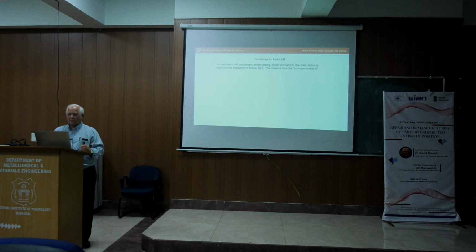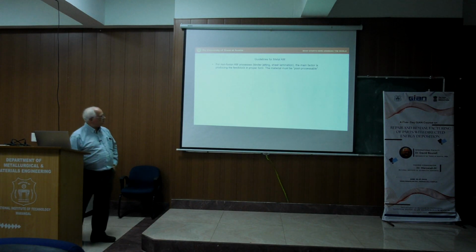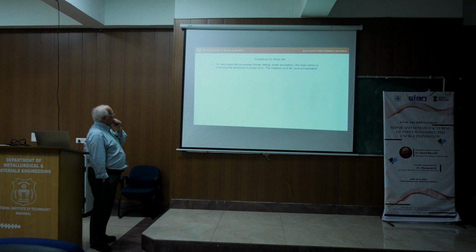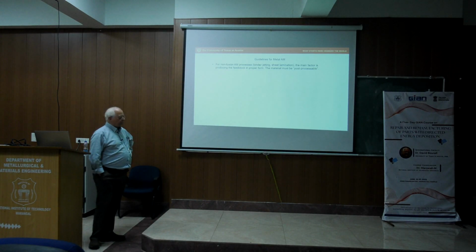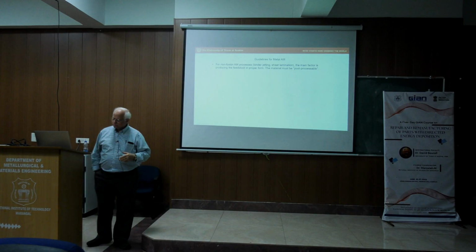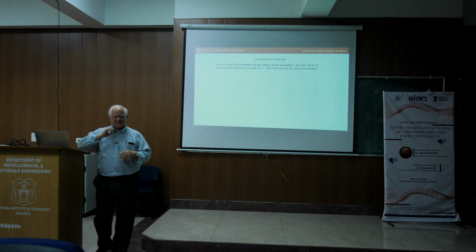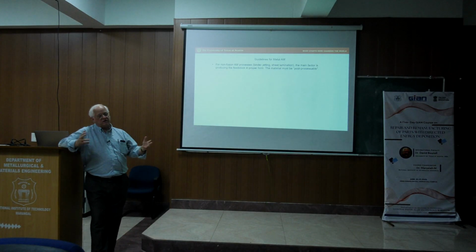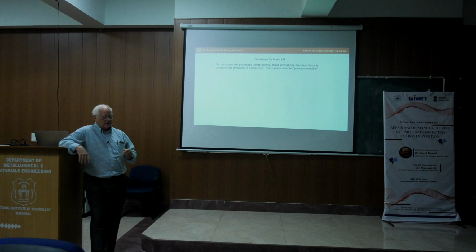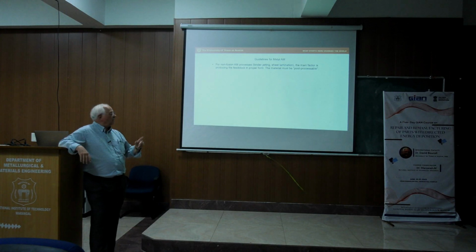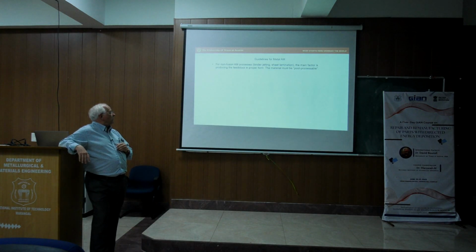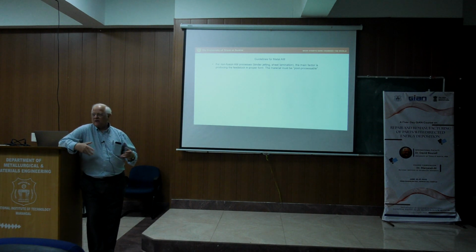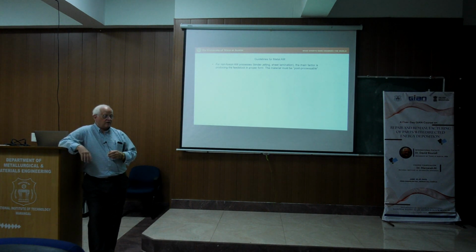Okay, so with that, let me talk about some general guidelines for metal additive manufacturing. This is general, but I'll try to emphasize the fusion part, which is what DED is. If we look at the various additive manufacturing classifications, remember there's 7 of them. Binder jetting and sheet lamination are 2 technologies that can be used to do additive manufacturing of metals.